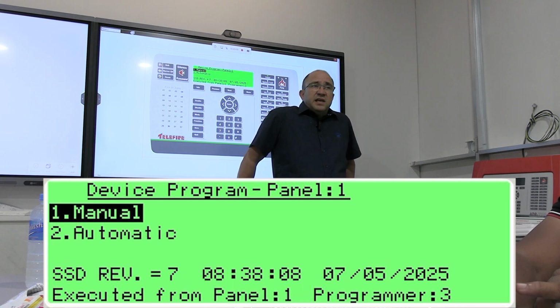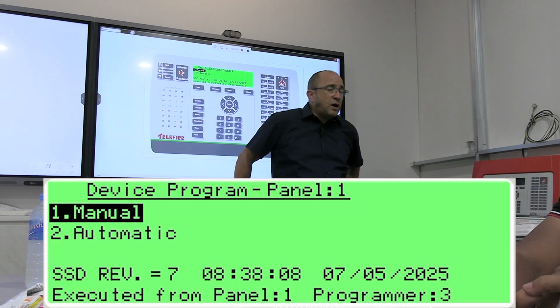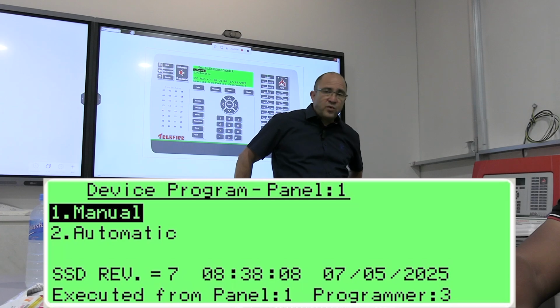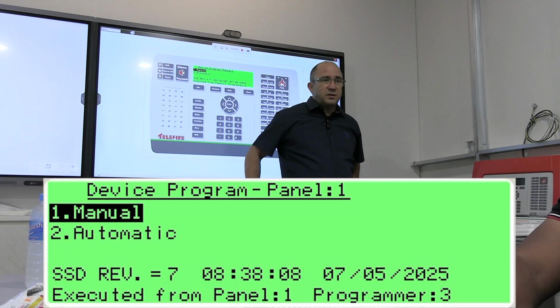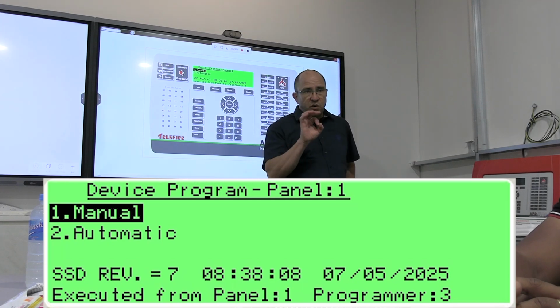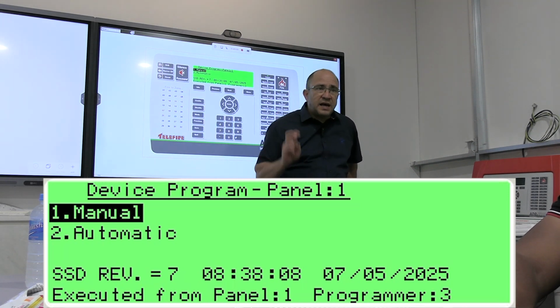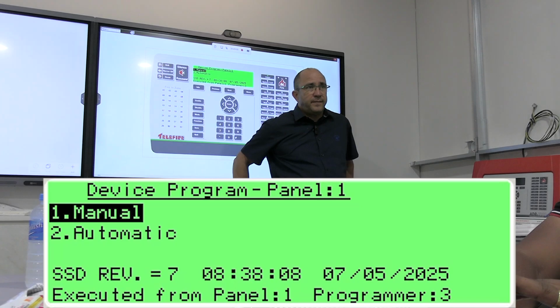Now, if you connected the extinguisher, let's say not very clever, to the output card, and you didn't change it, every alarm will activate the extinguisher. In other words, you connect the extinguisher only after you program the control panel perfectly, check that the output is working like what you programmed, and only before you leave the site.